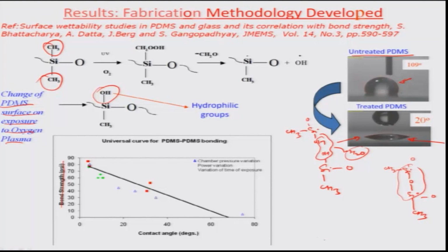intermediate region. So, the two surfaces which are now exposed to plasma can be brought close to each other to have an irreversible linkage with respect to each other, and we were trying to test the bond strength of such a surface. So, we had in fact generated a test for this which is known as a blister test.